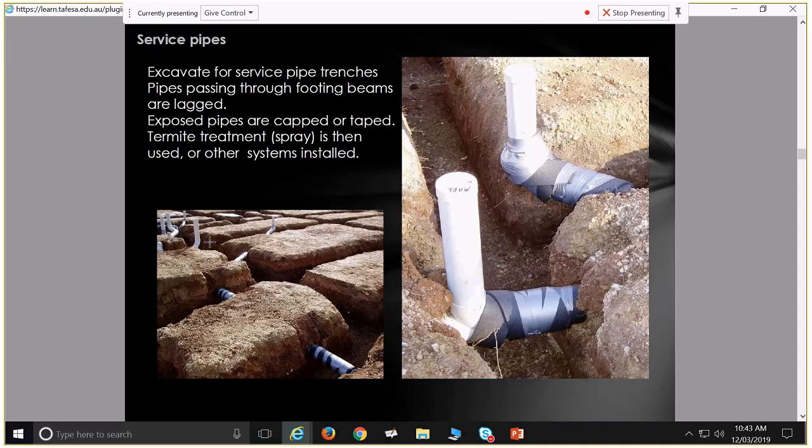Definitely. At that point in time, it's probably going to be a thing of saying to your client, look, that ship has sailed. We can't change our design now because we don't have any termite protection. If you want to have those exposed timber portal frames or whatever you've got as your new idea, I'm sorry. Because that happens at this stage: you're either dosing the soil with termite poison, or you're laying down a barrier that has the termite poison in it, or you go installing Termimesh, things like that.